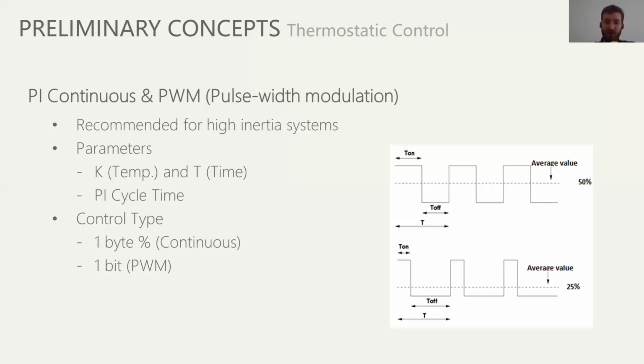That's, for example, to control a valve, a 3-point valve, where you can control whether the valve is completely open or closed. Where you can control intermediate values, and you can say, okay, open the valve, but don't open it completely, just open to 50% or to 60%. So the control you are doing with a PI continuous is actually how open the valve is. And if you have a valve where you can open it to 60, 70% or 20%, whatever values in between it can go.